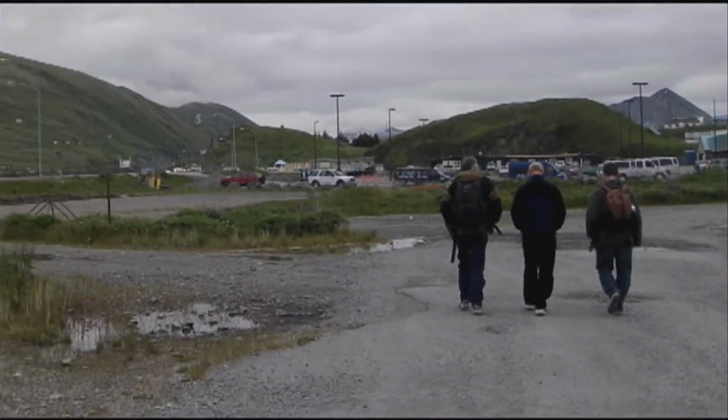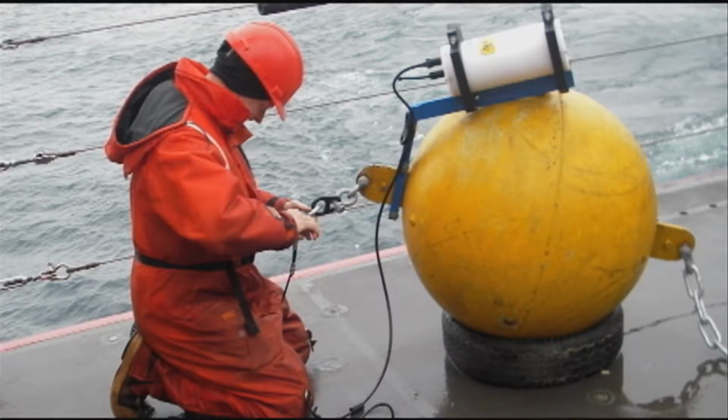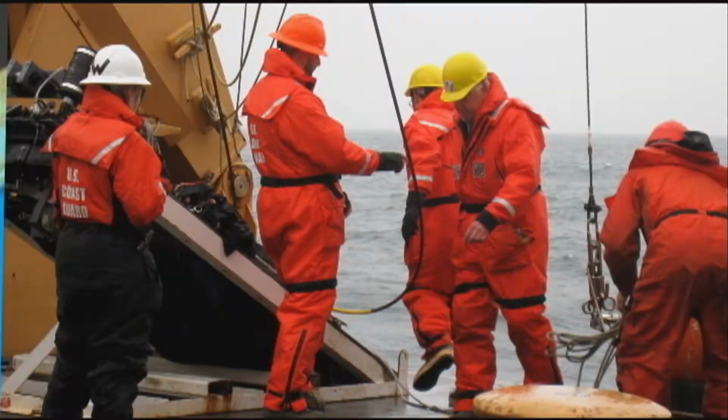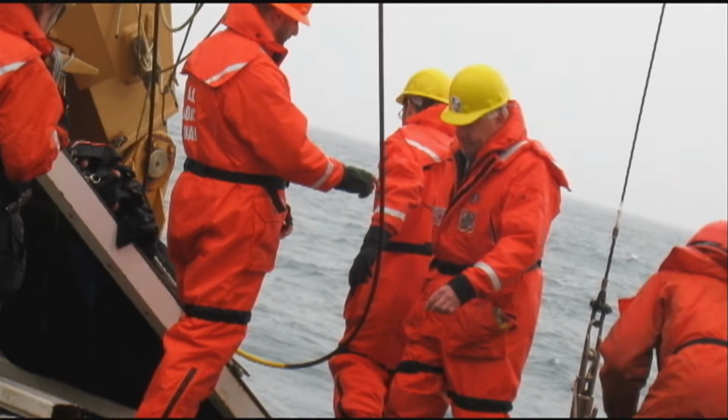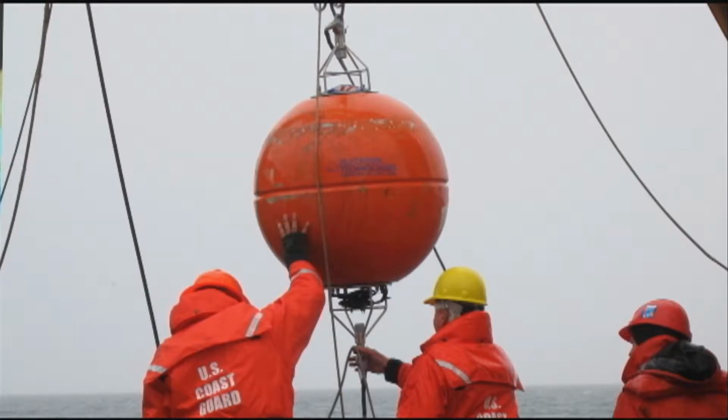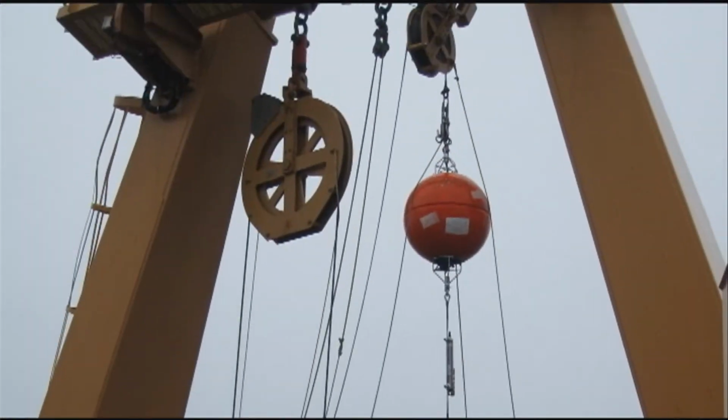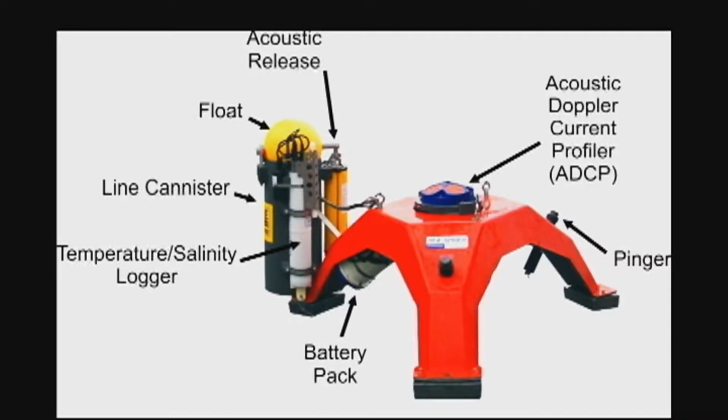We'll go out there in the summer months, because that's when you can get to these places, and deploy moorings, for instance, that are anchored to the bottom, and leave them there. Come back a year later, and with acoustics, trigger a release mechanism, and what happens is the anchor is let go of, the floats on the mooring bring everything up to the surface, and you pick it up, and then you can retrieve your data.